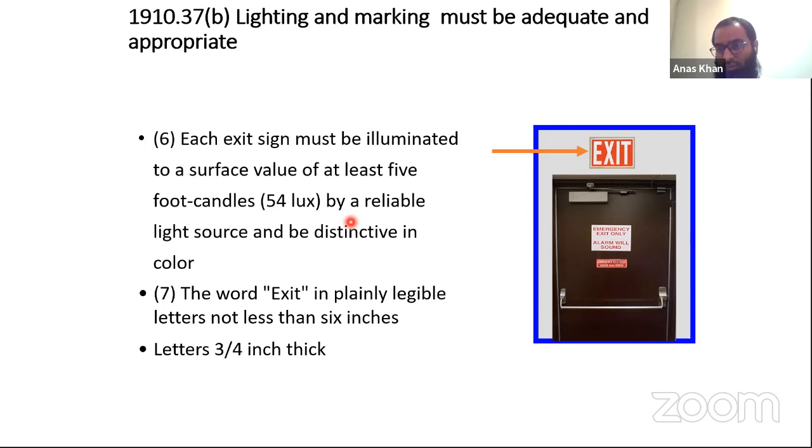Now what is your control? Sometimes they will say, see, we have a corridor, a lot of lights are available here to reach the emergency exit. So tell them, what if there is no light? What if you get a fire in your main electrical panel? There is no electricity, right? If the panel which provides the overall company electricity becomes out of order or catches fire, then what will happen? How are you going to provide the lighting? So in this kind of case, we need to have some lights available for emergency access, to the exit itself, and to the exit discharge.